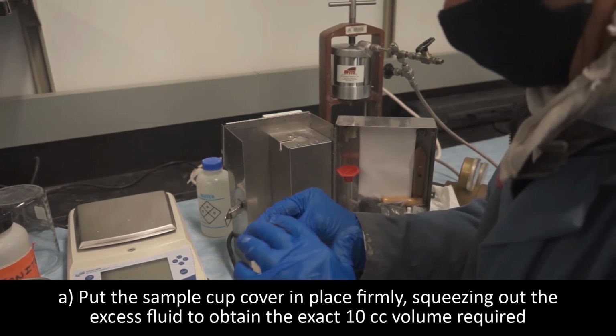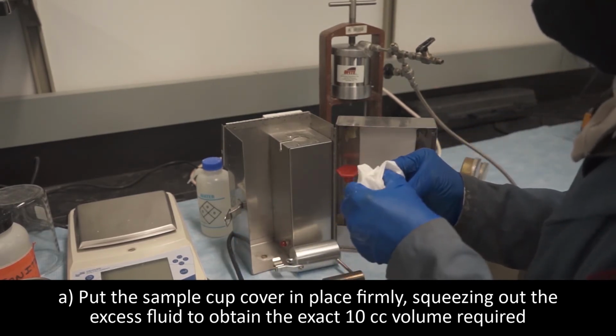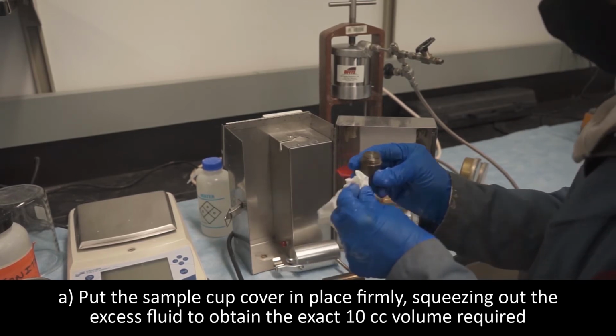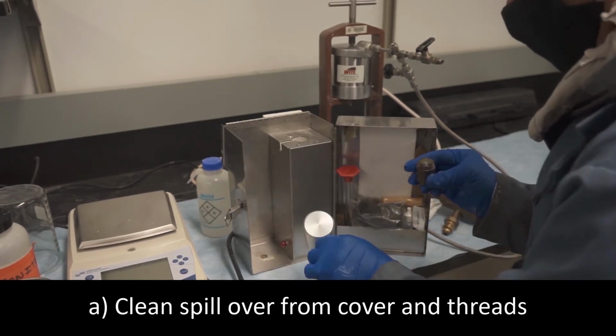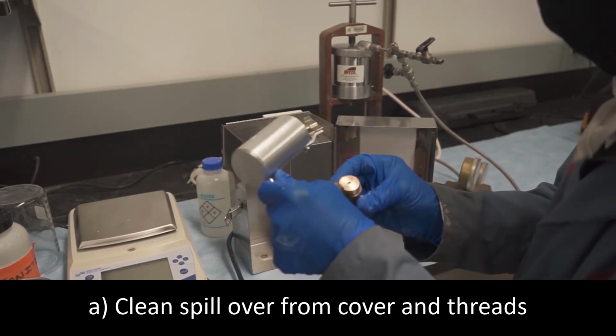Put the sample cover back in place firmly, squeezing out the excess fluid to obtain the exact 10 cc volume required. Clean spill over from cover and threads. If threads are coated with silicone grease, it will prevent sticking.